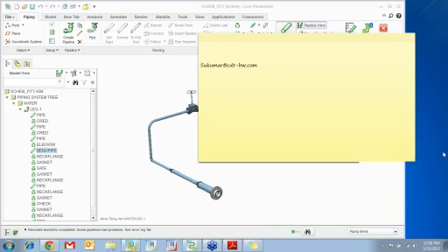The first question we have is, how does this work with flat ribbon cables, like the cable inside your computer for the floppy drive or IDE hard disk? Yes. So you have something called packaging inside cables. There's an icon called packaging. You can click on that packaging icon, and it will let you arrange your wires flat, or you can arrange them as a circle.